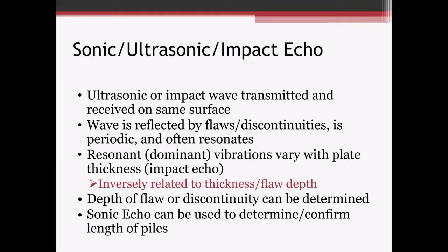You impact the top surface, and you wait for that wave to reflect from the bottom surface back up to the top. But remember what I said earlier about edge conditions. You have this long cylindrical member, and whatever wave you put on the surface is also going to be bouncing off the sides all the way down and all the way back up. So that can be a little tricky to process and understand.